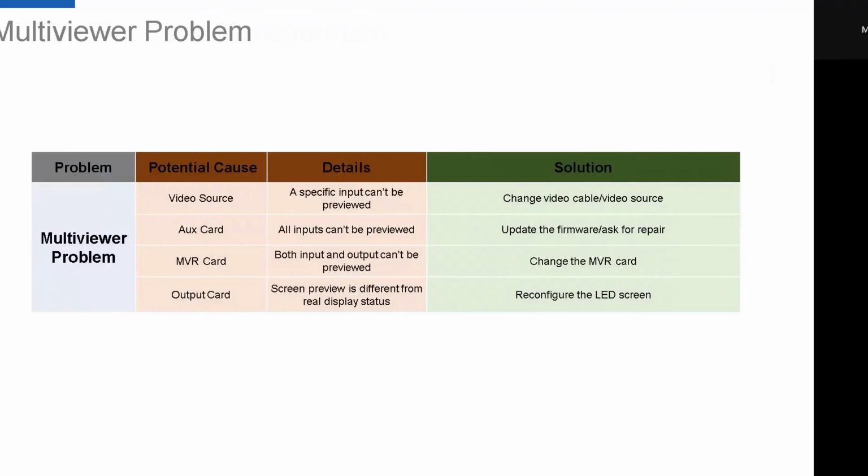First one: if just one of the inputs cannot be previewed, there is a big chance it's caused by the video source. So we need to change the video cable. If it still doesn't work, try changing to a different video source and see what happens.